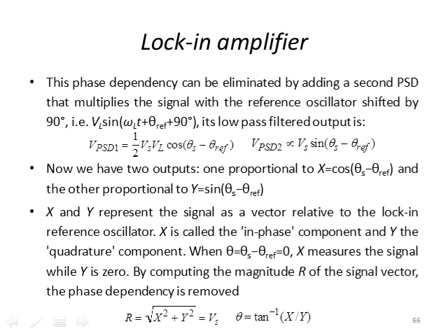And you can go through these calculations and you can see that using this type of arrangement, using this concept of synchronous demodulation, and also this lock-in technique, allows us to measure signals that are far, far smaller than the noise signal, which was described early in the course as being very, very difficult to do.